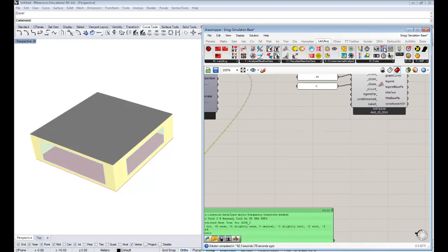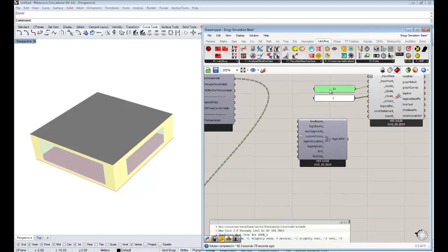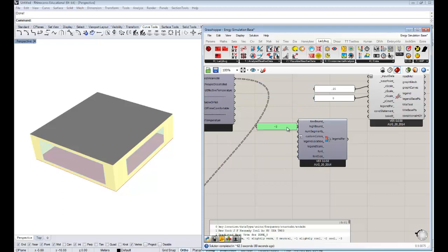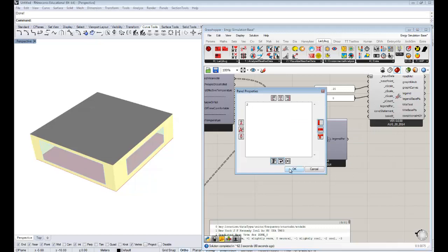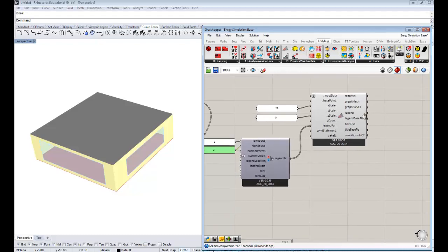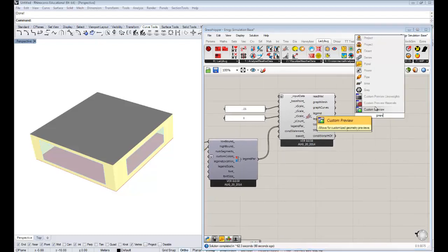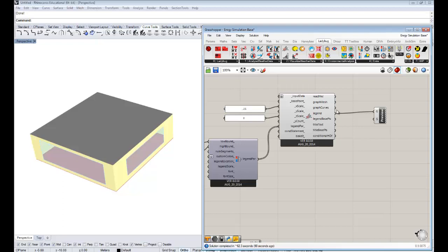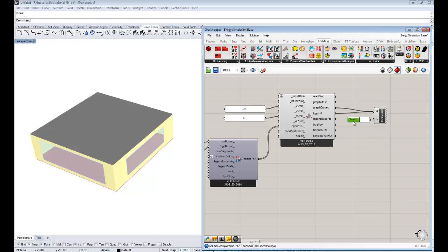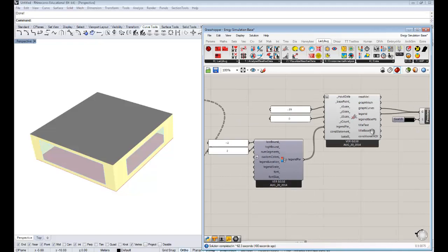Then we'll also put in some legend parameters. We'll set a low boundary of the lowest possible. Well, let's see, I don't imagine us getting a predicted mean vote worse than negative 2 in some cases. And then we'll set the upper bound to be positive 2, and plug those into our legend par. Looks like we're basically ready. Then I'll do the preview I like with the graph curves and the swatch. Okay, all right, so now we're all set up.